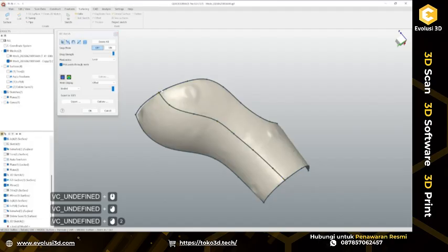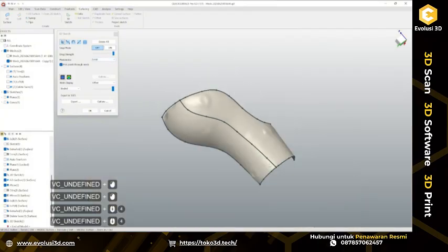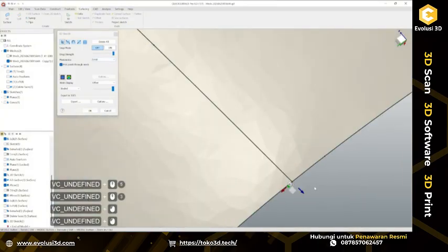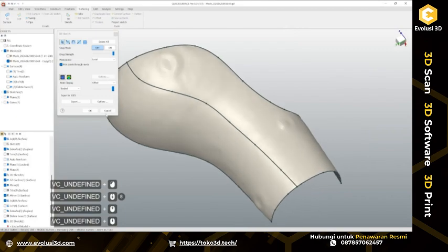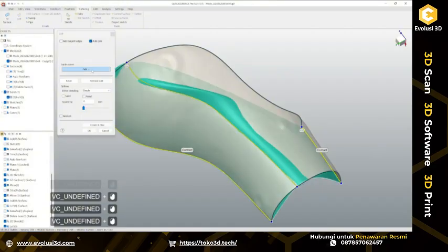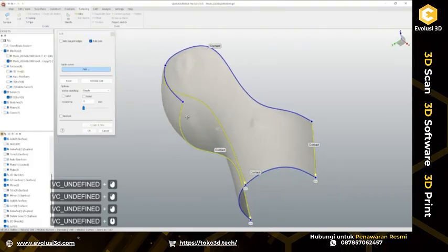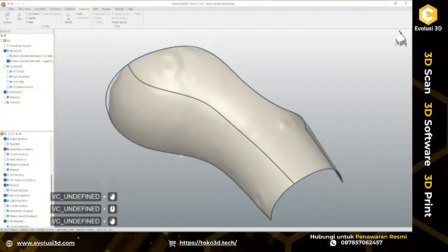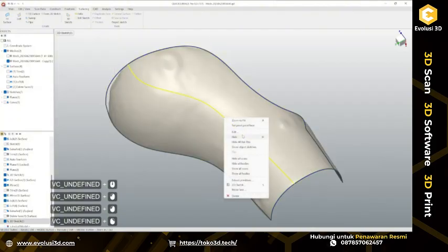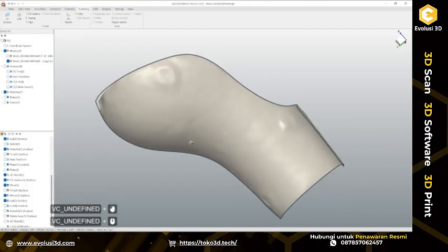Of course, we always have to check if we have a snap to our guide curves, but in most cases when it starts to fail, it's just because the result of this loft creates self-intersection. So yes, as you can see, it's failing. Basically, it should look super simple, just draw a couple of guide curves and, well, you're ready to go. But no, it's far from that.